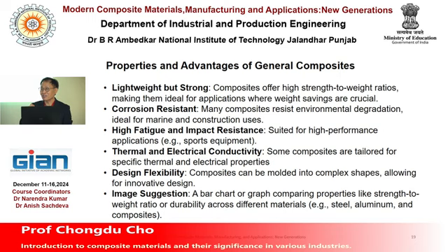Very, very expensive. But if you can make it based on nanoparticle-based composite material, you can do it. Then in that case it will be very nice. For example, if you need very poor thermal conductivity but very good electrical conduction, in that case just 4% of carbon nanotube can be used together with the resin.